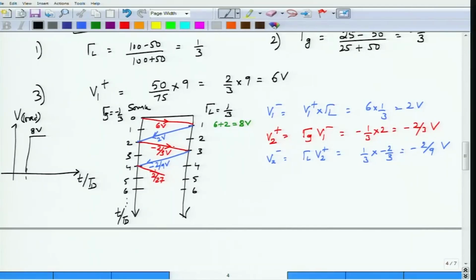So, at 3 milliseconds what would be the total voltage? Whatever the initial voltage that is there plus the voltage that is now here. So, this would be minus 2 by 3 plus minus 2 by 9. Okay. So, this is minus of 2 by, so 2 into 3 you can do, and this would be 9 plus 2 by 9, right. So, this would be 6 plus 2, this is around minus 8 by 9. So, approximately minus 1 volt.